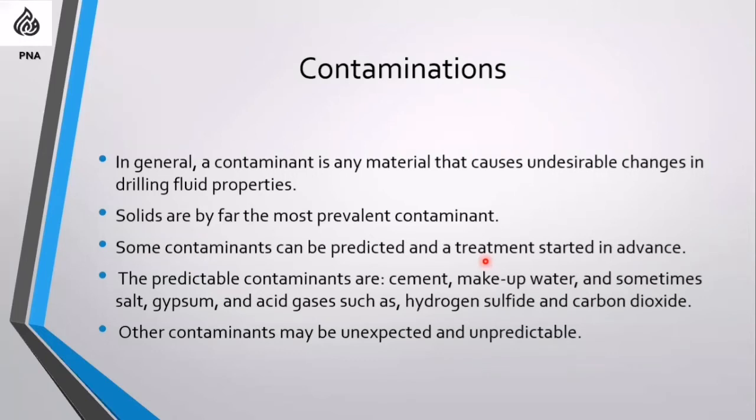For cement, we know before drilling that we will get cement contamination, so we can pre-treat. Makeup water also: before mixing, we know our makeup water has some hardness, some calcium, some magnesium, so we will treat it first, then add other chemicals to mix our mud. Other contaminants may be unexpected and unpredictable because they come while drilling.